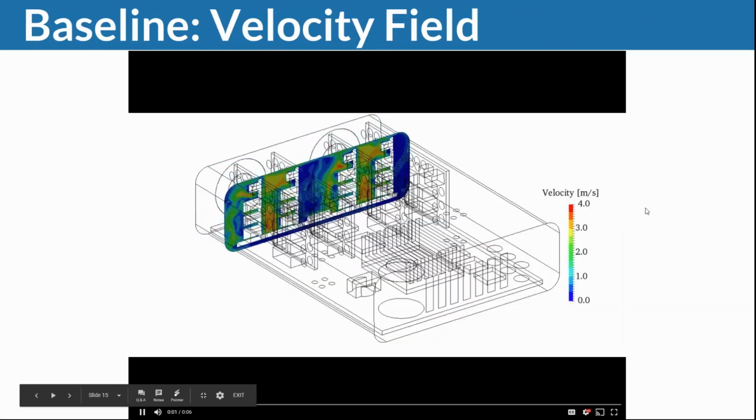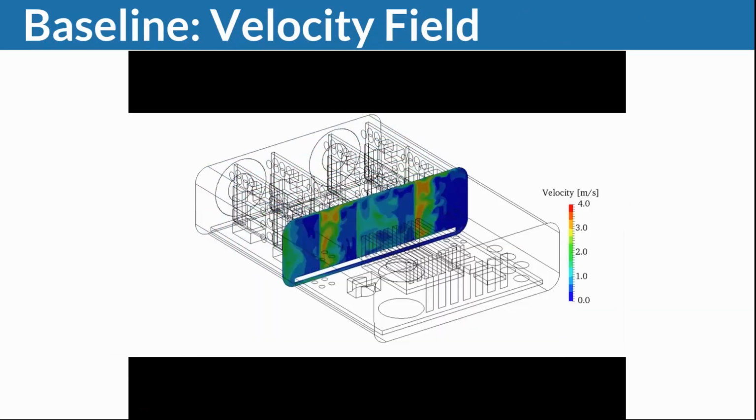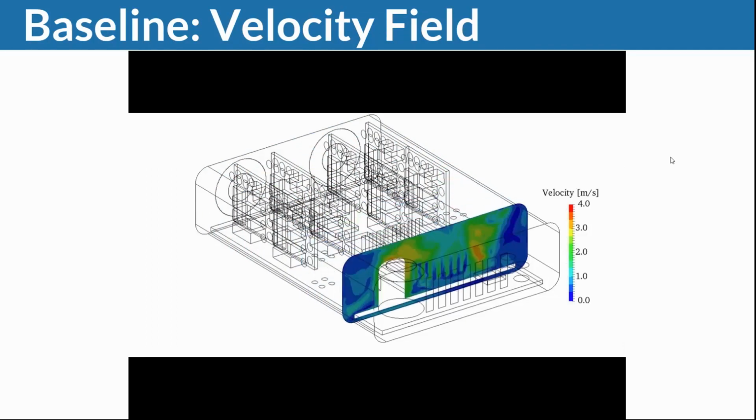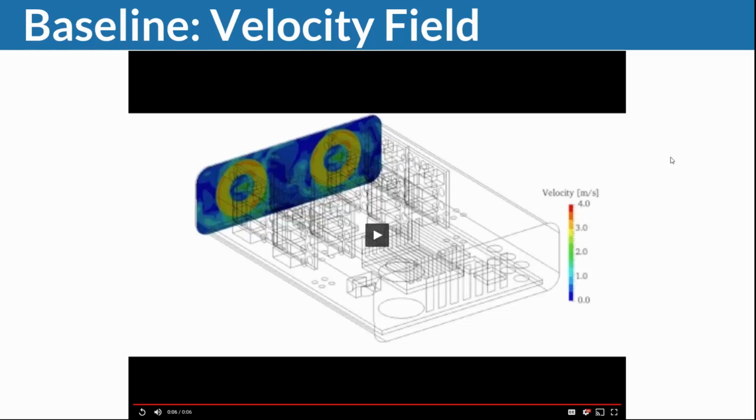What you'll get out of a simulation result on SimScale, out of such an analysis, is all the result values, meaning temperatures, velocities, pressures, turbulent quantities, within the solids and within your fluid regions. Obviously, velocity and pressure only in the fluid regions.